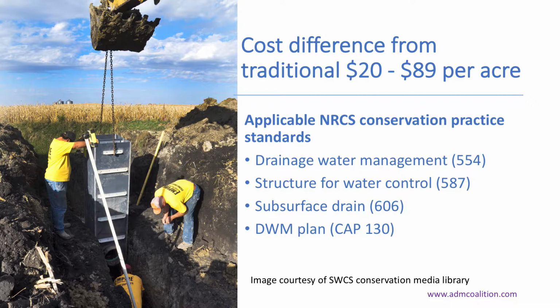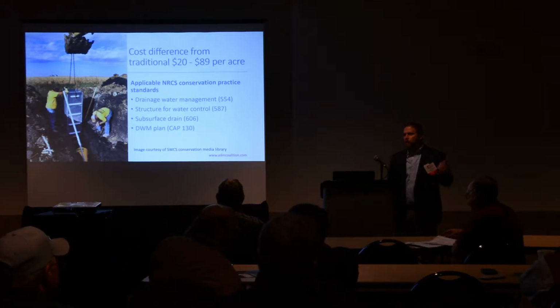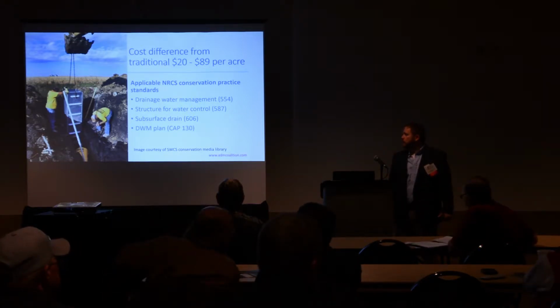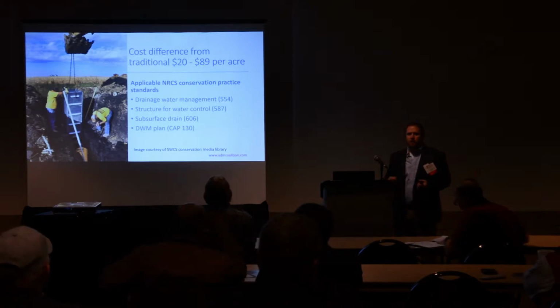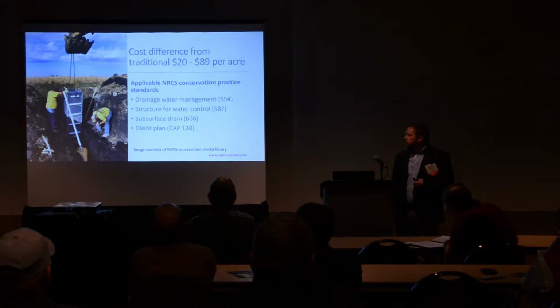Also, they do pay for some of the tiling system that's associated with drainage water management. Sometimes with the design of these, you need a sub-main that probably wouldn't have needed to be there in a conventional system to help control that water. And so there's cost share available for those sub-mains if you have to put in additional sub-mains with that plan. Then also there's a drainage water management plan itself, so CAP 130. We heard a little bit about some of the other CAP programs in the previous presentation. To actually write that management of how to handle those stop logs throughout the season, there is some funding available for TSPs to help their clients with that.